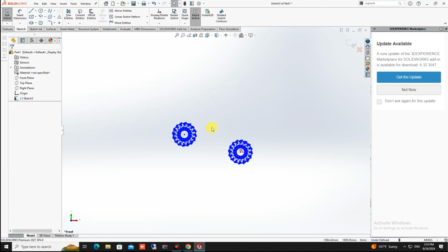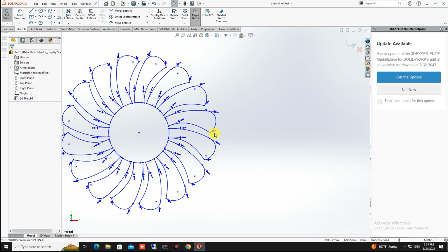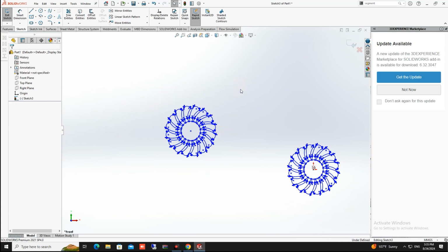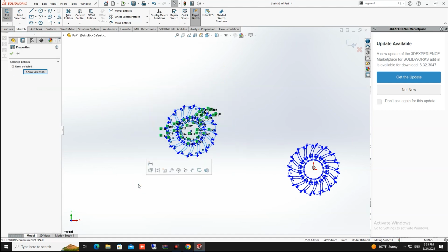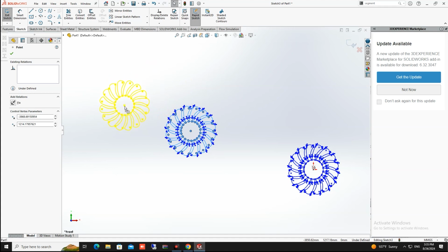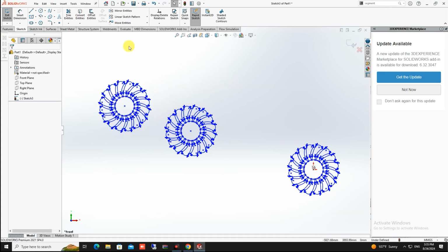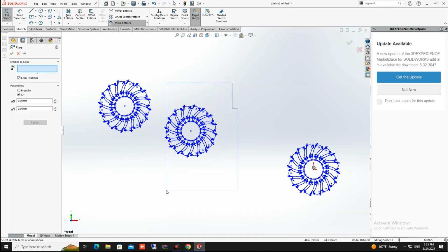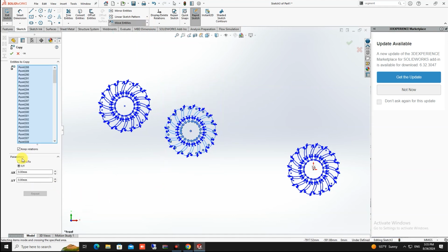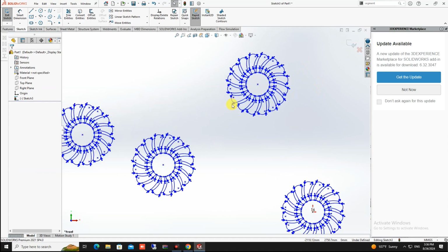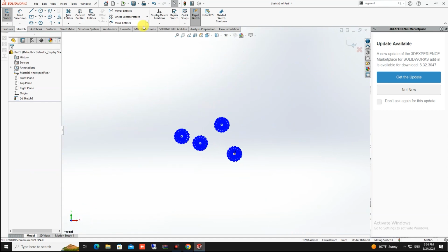The other, as you could see, if I wanted to copy some parts of a sketch, I would hold Control. As you can see now, I hold Control and will take one of the points and make another, as you can see. The other way is to click on this one, copy. I will choose all of it, for example. Then, for example, I choose from to, like moving. I will choose a point and make a copy of a part of a sketch.